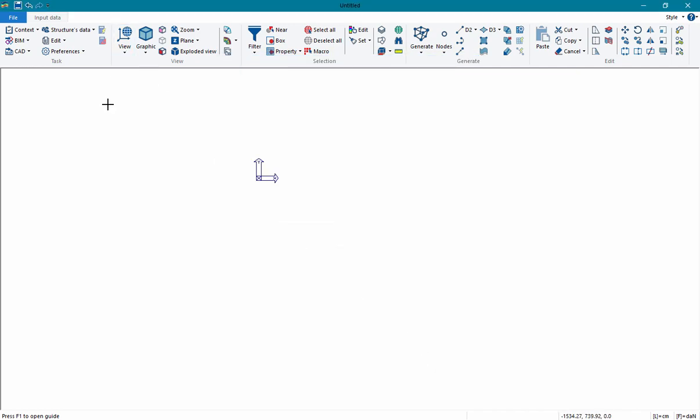To model a structure with ProSap, we can import a DXF file from AutoCAD or also an IFC file. ProSap also has a set of automatic generator of structures. For example, to model a concrete frame, we can use its generator of frames,